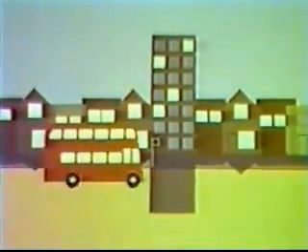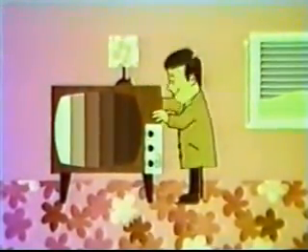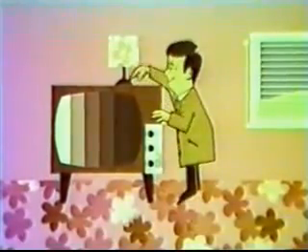This is a warmer white than on monochrome receivers, and the white must be correct not only at full brightness, but also at all levels throughout the gray scale. If this is not done, the picture of a bus, for example, which appears bright red in sunlight, would change color when the bus moved into the shade. This is gray tracking, and because of the importance of getting the right adjustment near black level, it cannot be carried out in a lighted room.